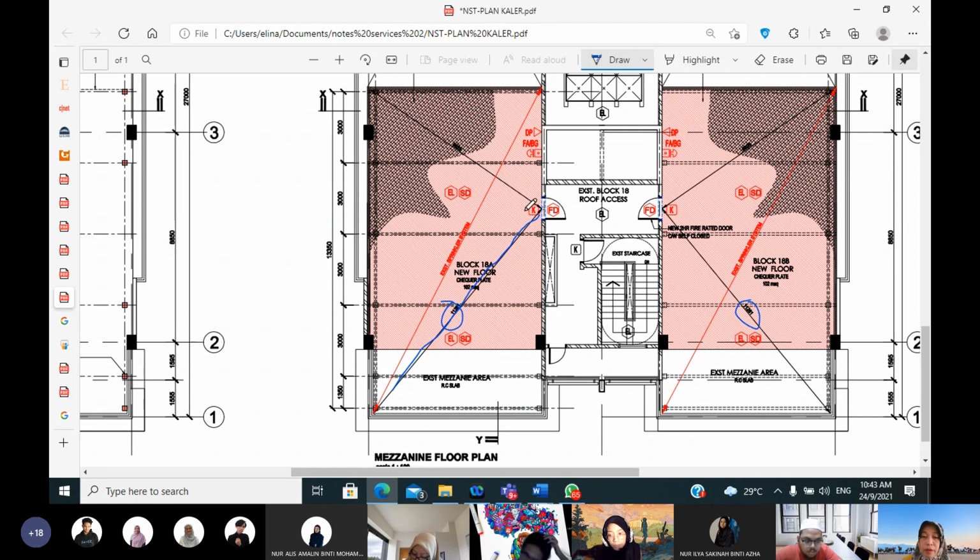Okay. FD is fire door. K is for exit; in Bahasa we call it keluar. DP is your dry powder, your fire extinguisher. SD is your smoke detector. EL is your emergency light. But today we just learn how to indicate the fire staircase according to travel distance. Okay.